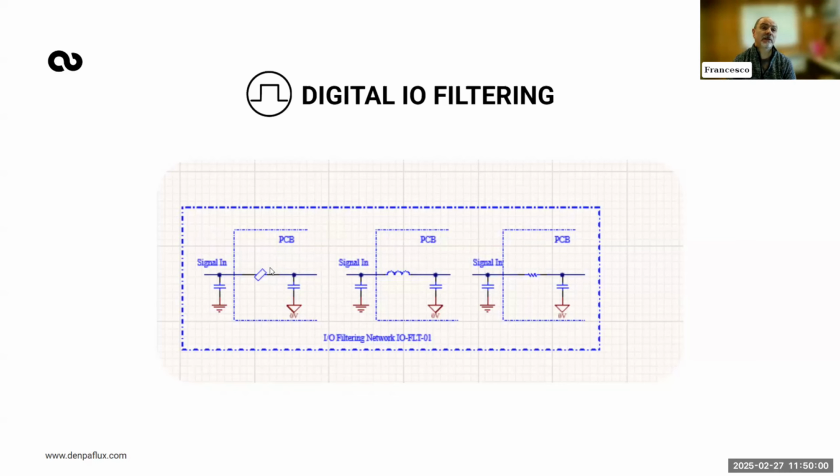So now, every connector, I try to protect every single digital input or analog input in a very wide frequency range. And I do this by adding, I do not fit varistor or I do not fit ferrite, inductance or resistance, and some do not fit capacitance. If during the test I fail, I fit them.